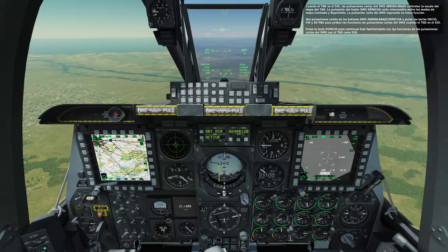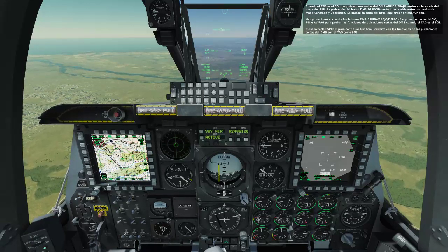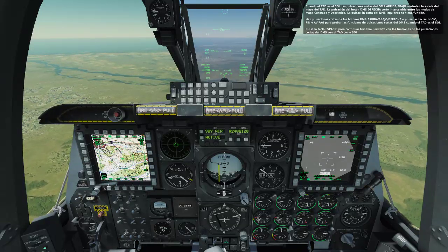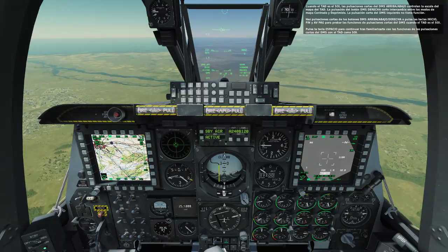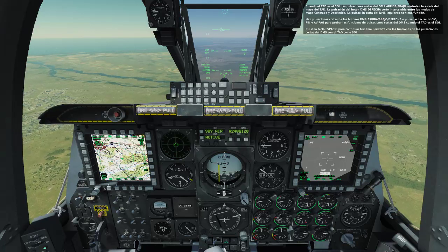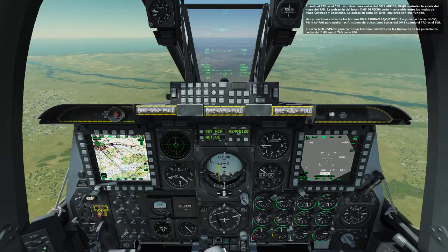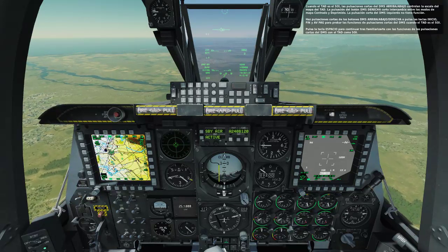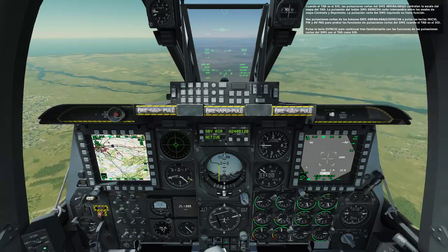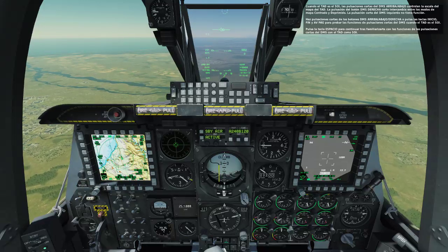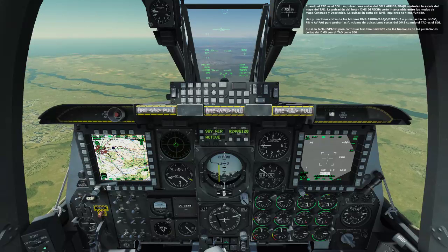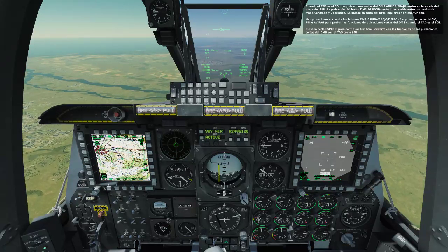When the TAD is SOI, the DMS up-down short commands control the TAD map scale. The DMS right short command switches between centered and depressed map modes. The DMS left short command has no function. Press the DMS up, down, right short commands or the home, end, and page down keys on the keyboard to try the DMS short functions with the TAD set as SOI. Press the spacebar key to proceed after becoming familiar with the TAD SOI DMS short command functions.